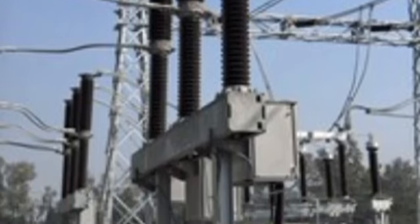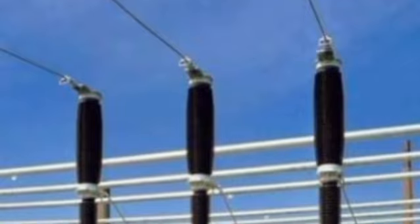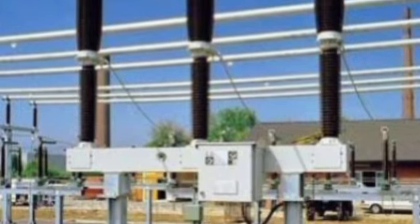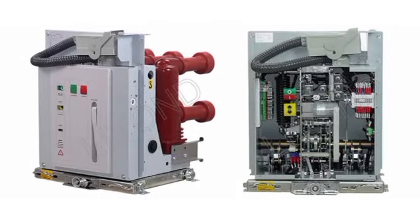In a 132 kV substation, circuit breakers may include SF6 circuit breaker, which uses sulfur hexafluoride gas for arc extinguishing during fault conditions. Vacuum circuit breaker, VCB, uses a vacuum to interrupt current and is generally used for medium voltage but can be applied at 132 kV in certain designs.